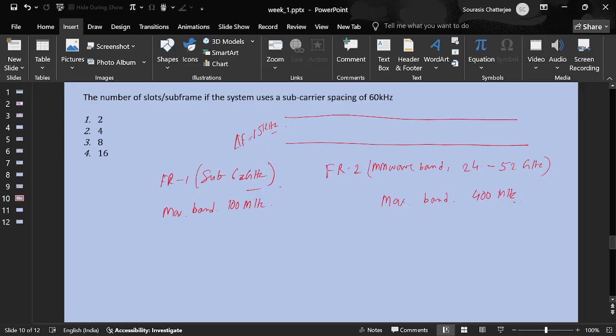Usually maybe every slot. Yeah, so every slot the base station usually makes a decision. So in every slot you have 14 symbols, and this is a good point to introduce that in OFDM we are basically mapping symbols in a time frequency grid here.